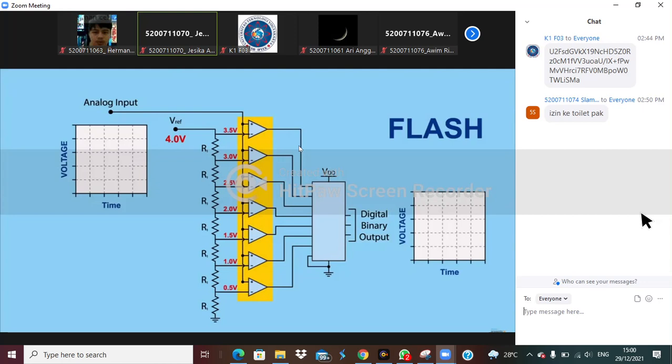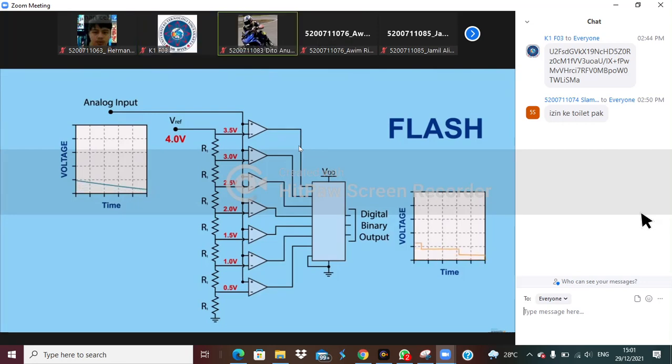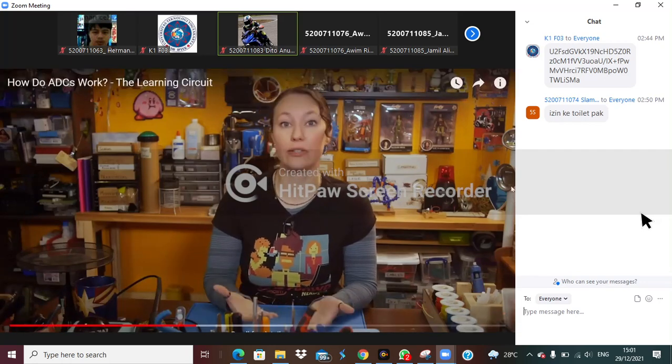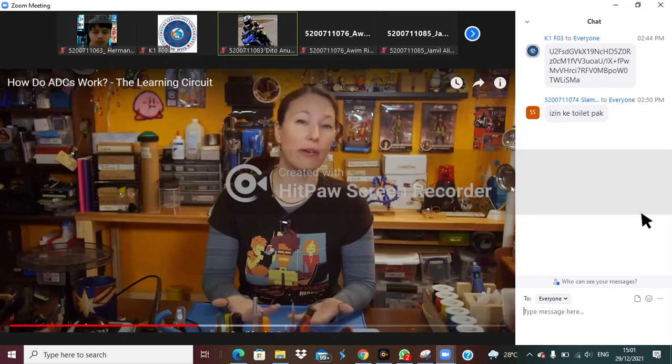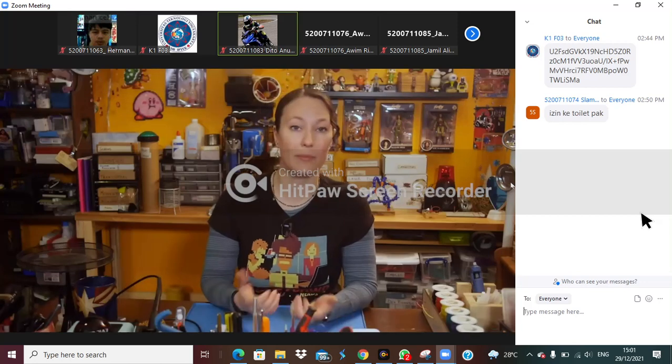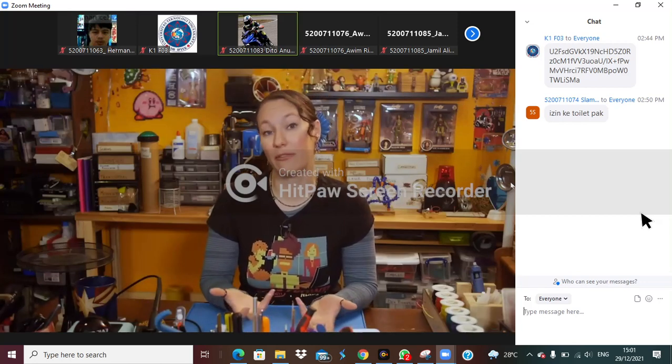Each comparator connects to the analog input signal, as well as a voltage divider that splits the reference voltage. The comparators process their signals simultaneously, each outputting a 0 or 1 accordingly. The comparators feed into a logic circuit, which processes the data and outputs the 3-bit binary number. The analog input wave is converted to a 3-bit digital wave. This style of ADC is great for how fast and efficient it can convert the signals due to its parallel processing. However, given the large number of comparators needed, and since each bit requires its own output pin, chips can quickly become large and expensive to manufacture.